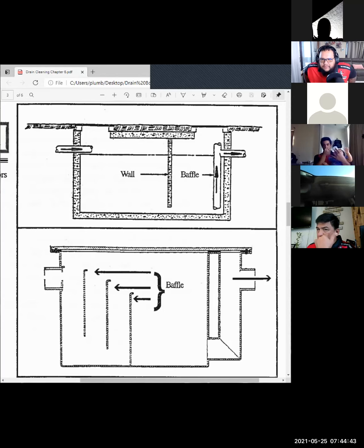Josh, let me help you here, because there's a real misconception. I'm going to take you guys through a real case scenario here, and I'm going to use the word mantle. So Josh has his arrow there on the water level, and you see a wall, the baffle, the inlet, the exit. Above that you have the manholes and the entrance, and you can look in there and see a big thick layer of grease, and you tell the guy, hey, this thing is full.